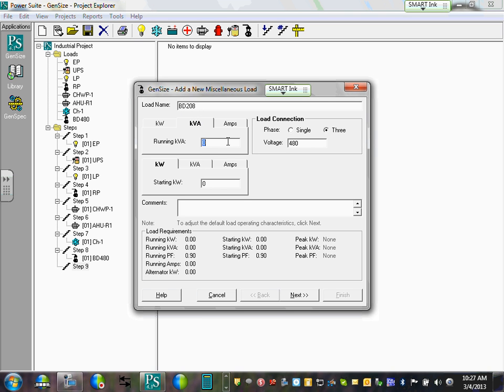What's the KVA again? 152 KVA. Again, you guys are going to use your own. I hope I wouldn't see these numbers in your calc. You're going to use your own numbers. Remember, this one is 3-phase 208 though. 208, right? There was a 208 system. I changed it. I'm going to double this one, so that will give me 304.